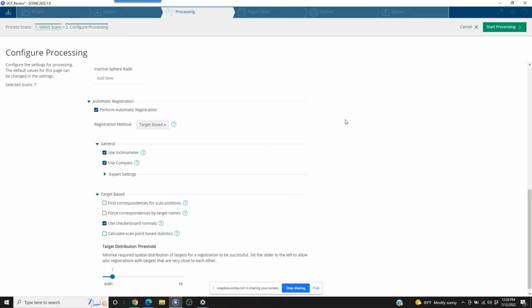We'll go through this when I drop the scanner off, but you get 6 sphere targets. You put them out in an array around the scanner. You don't want them more than 30 or 40 feet away at the most, because a certain number of laser points have to make contact with each sphere in order to be able to identify that as a target. Then you're going to move the scanner. And when you move the scanner, say 50 feet, you can only move 3 of the 6 targets.